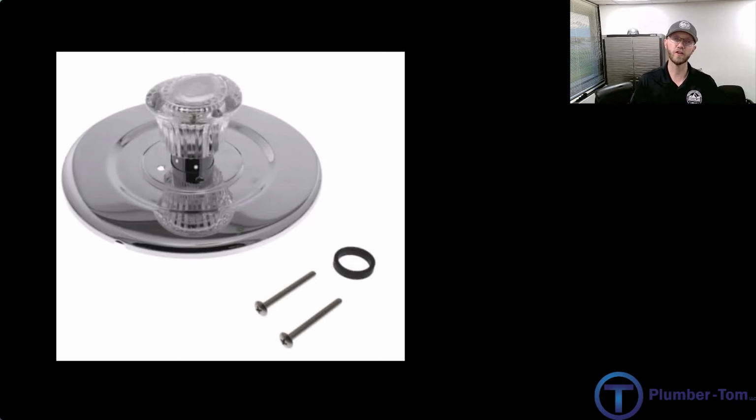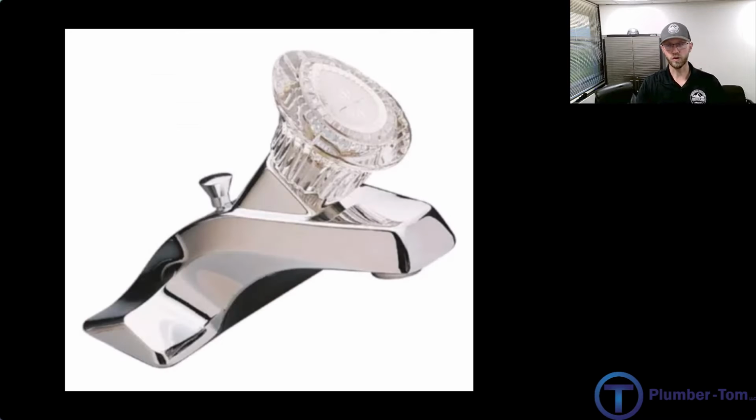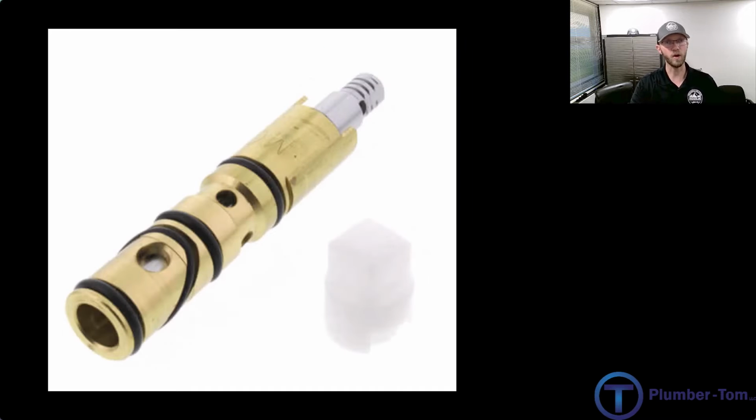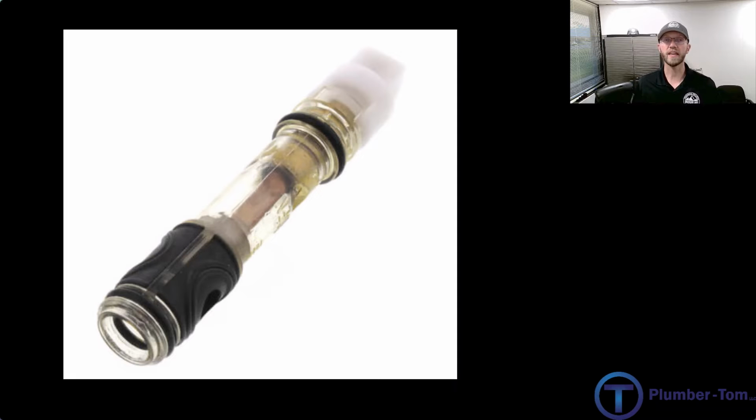Moen. The Moen Troll single-handle faucets that have been installed and used for decades had a single handle, a single cartridge inside of there, and it would control hot and cold. That was fine for a long time, but as they wear out, particularly the older brass cartridges, they allow for crossover. I've helped many customers who've had problems either not getting hot water where they want or getting cold where it shouldn't be and running into all kinds of issues. And once we take out that cartridge and replace it with a newer plastic one, problems go away. It seals it right up.